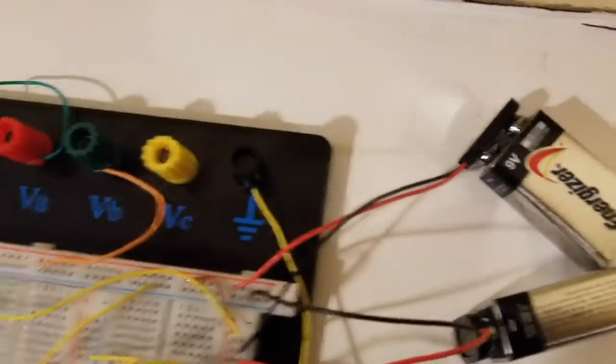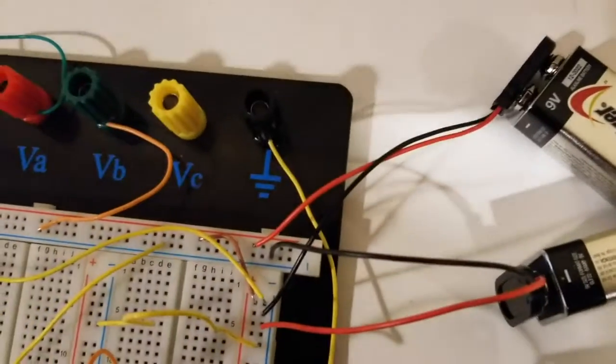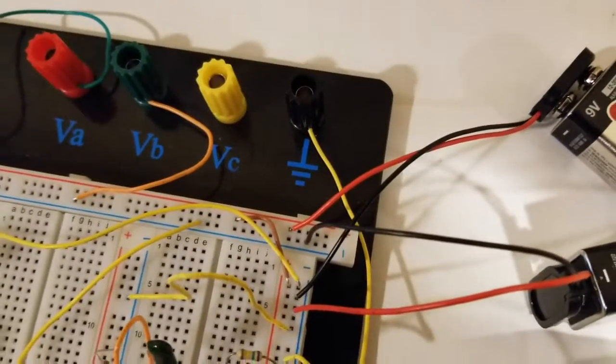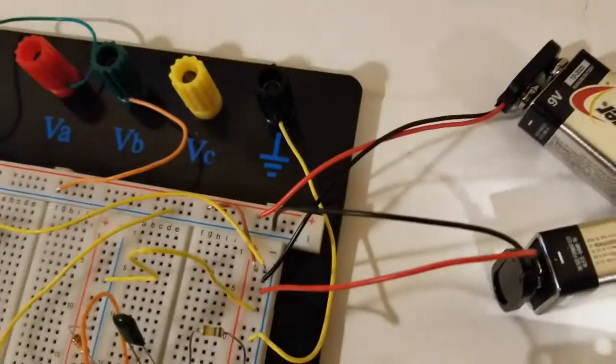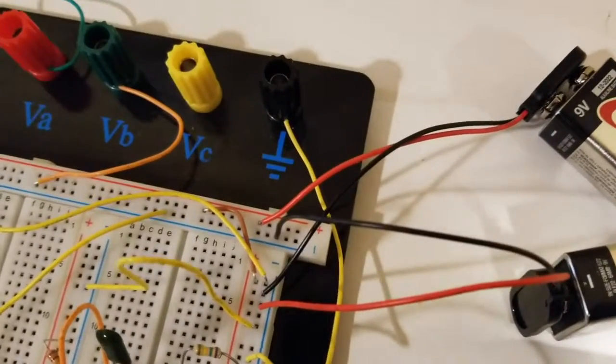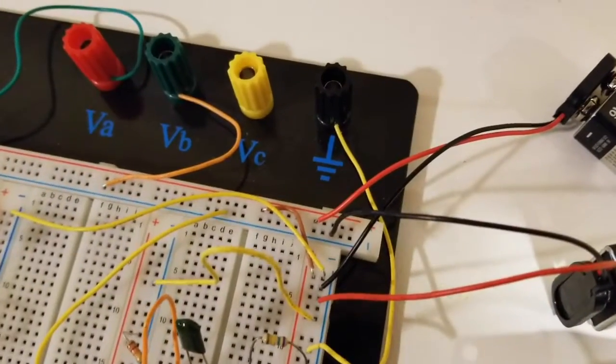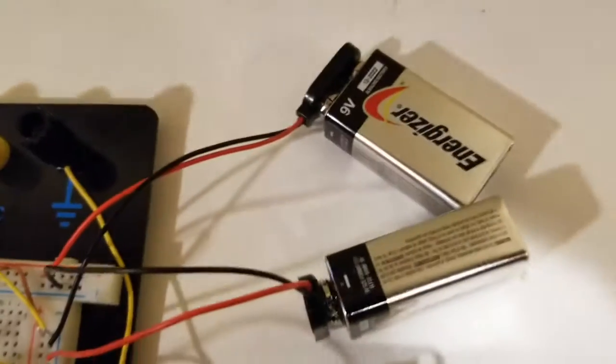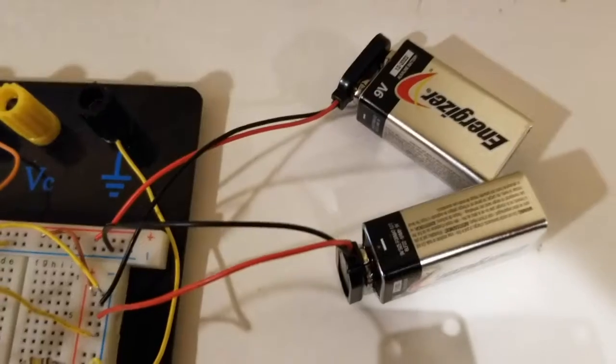With the batteries, we have 2 9-volt batteries here. One of the positive ends is connected to the positive rail, and then the negative rail is connected into the ground rail. And the positive from the other is connected into the ground rail, while that negative is connected into the negative rail. So that basically allows us to have a ground as well as +9 and -9 voltage going into the circuit, which is what we needed because 4.5 was a little too low.